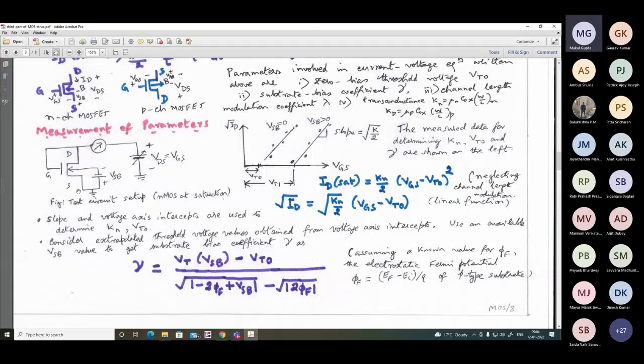Why? Because source is an N plus junction, drain is an N plus junction, and body is a mildly doped P-type substrate. So this PN plus junction remains reverse bias, right? Because P is connected to the negative pole. It will not violate that, so this will work. I'm sorry, I was just having in mind multiple connections like cascode connection. When we are considering those connections, then source cannot be grounded.